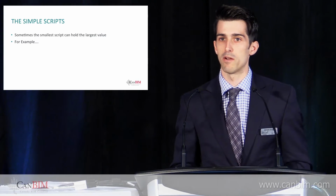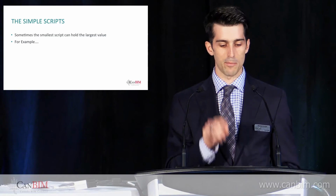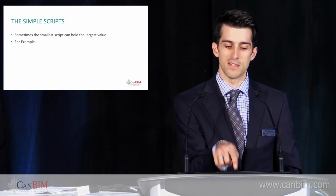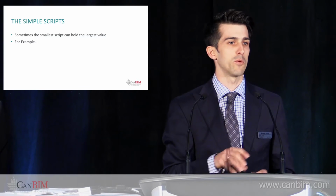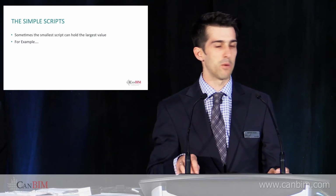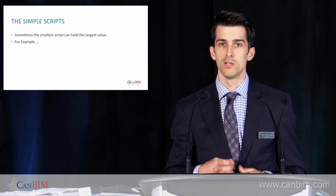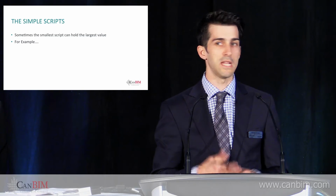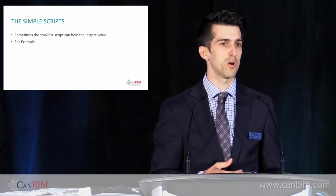If I have a standard library filled with typical details, the person using the Excel sheet can go in and say, from a project management standpoint, I need this wall type, this stair type, this thing. Then we hit go in Dynamo, and it will populate the entire sheet until it reaches the very end. Once it's done with that sheet, it'll open up a new sheet, rename it, populate it, and keep going. These tasks take a long time in a building information model world, even in the CAD world, where we used to use Autolisp. It's no different. This is the new Autolisp. This is Dynamo.